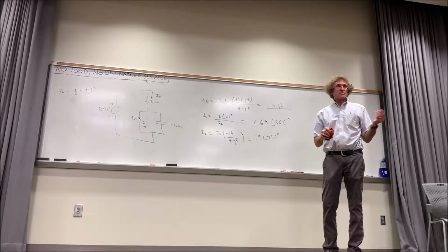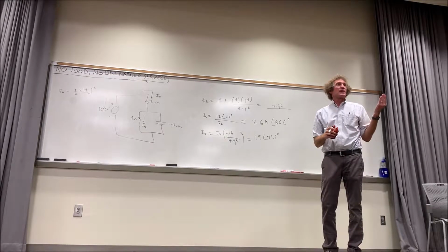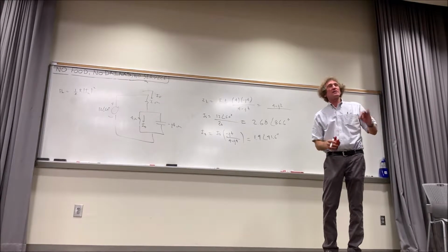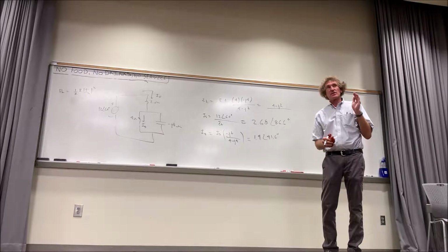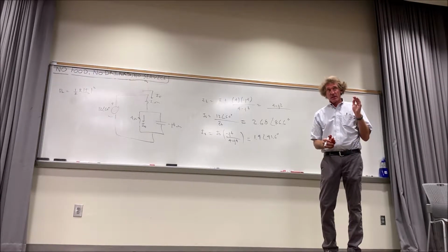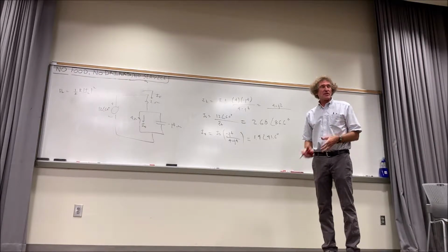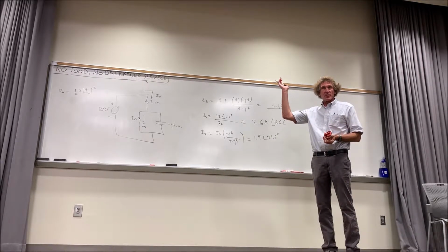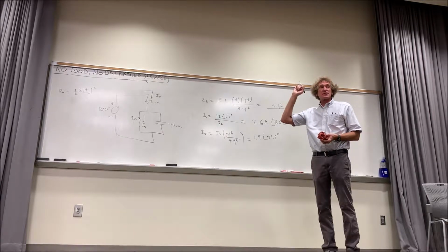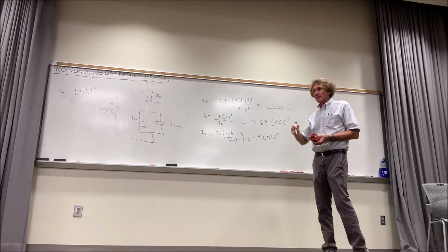All right. Now, once we have the currents, we've got the average power. These are peak values of current. They are not RMS. If I wanted the RMS value, what do I have to do? One single thing. If you did the problems, remember. I take the peak value and divide by the square root of 2, or multiply by 0.707. How many of you remember that from the lecture? Remember, you're going to be asked to do this a lot. So you have to get familiar with peak versus RMS, root mean squared value.